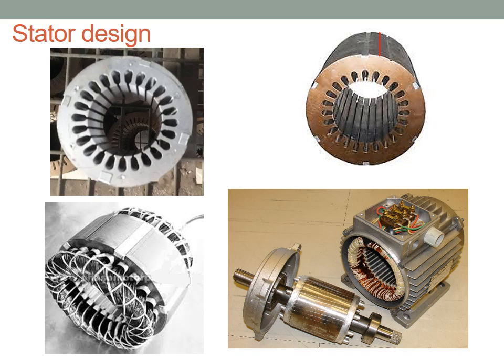So you can see here, in this stamping there are a number of stator slots. Along with that, there is a tooth. So there are a number of stator slots embedded over the periphery of the stampings. These are the slots where the winding is embedded, and along with that, the stator tooth comes. Now you can see in this picture, the winding is embedded in the slot.